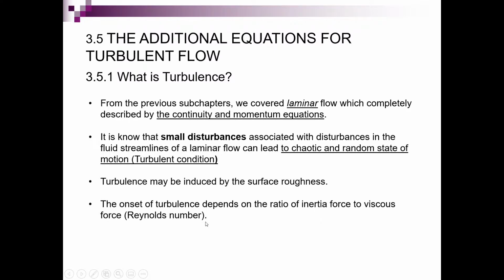Meanwhile, for turbulent flow, Reynolds number is high, which means the other way around: inertial force is higher compared to viscous force. The easiest analogy is that laminar is highly ordered flow, meanwhile turbulent is highly disordered flow, which is hard to control. Laminar is easy to predict because it is very organized.